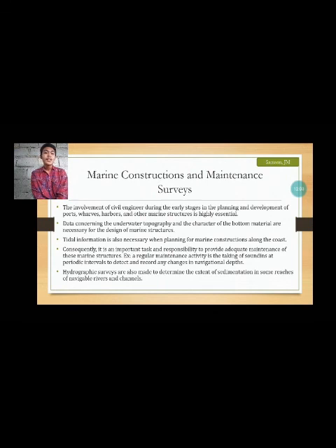Example, a regular maintenance activity is the taking of soundings at periodic intervals to detect and record any changes in navigational depths. Next, hydrographic surveys are also made to determine the extent of sedimentation in some reaches of navigable rivers and channels.